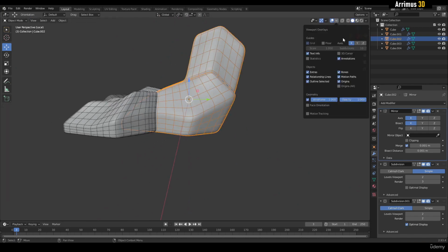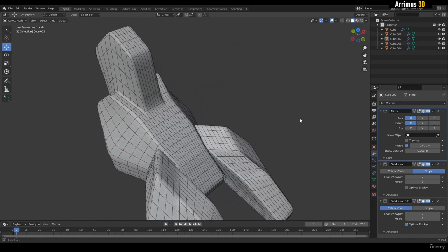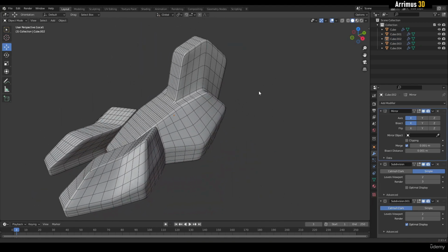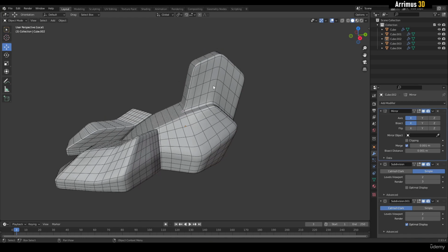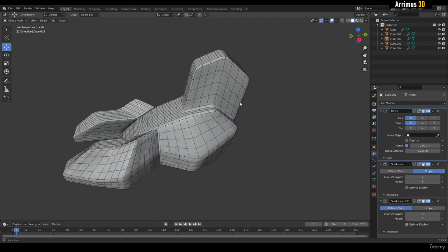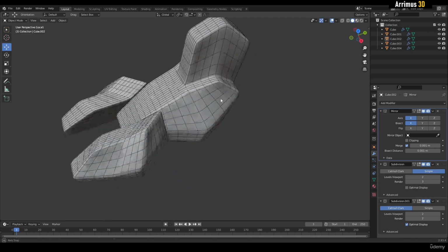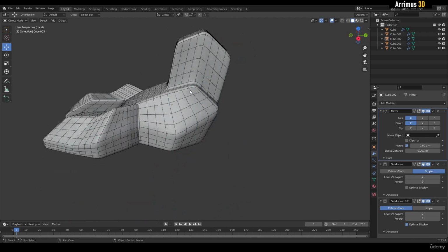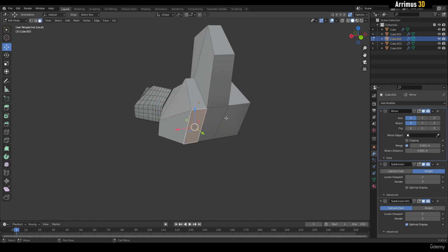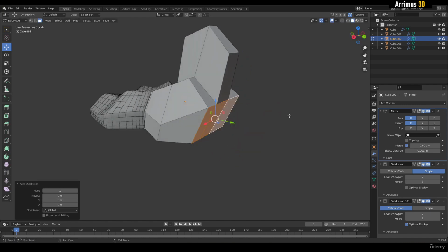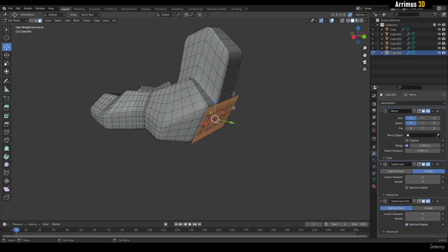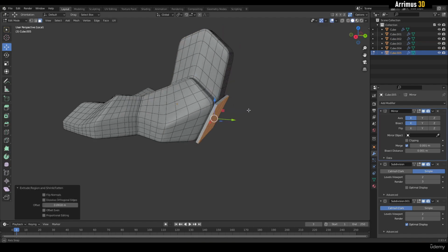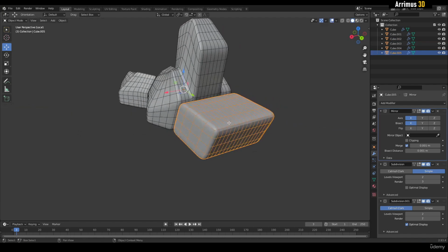We can even turn off the x-axis and just keep looking at this. Now, one bad thing about this method is that we can't really use circular shapes until the end because they're just going to become angular. For example, I can select this, hold Control left click here, Shift D right click, P, select the new object, Tab, A, extrude a little bit here, then move it myself.